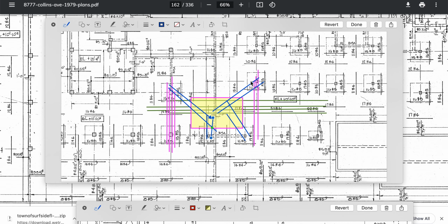And then we still have to tie it back. That's just holding there. If you do that, all four posts are going to fall in. So you have to tie it all the way back to the walls and keep going back, so there's no deflection. You want no deflection here. Because deflection is going to pull the other columns in, put a stress at the joints, and start pulling on the next slab over. So you want to make this so it doesn't deflect.